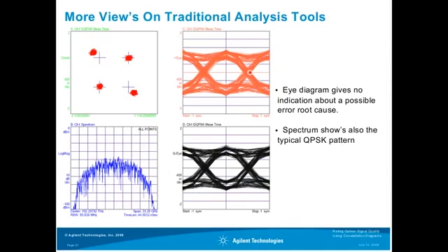Another offset that might occur during the design of a transmitter, for example, is the IQ offset. The IQ offset simply describes the offset of the constellation diagram from the origin. Again, the cross points are the ideal points, and here we see the measured squared constellation diagram.